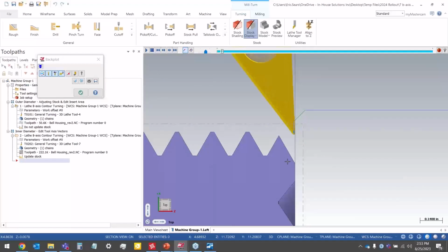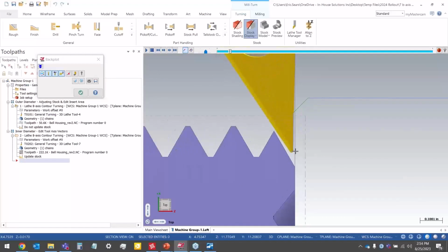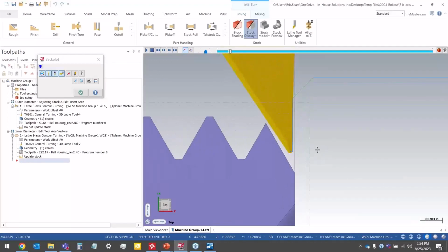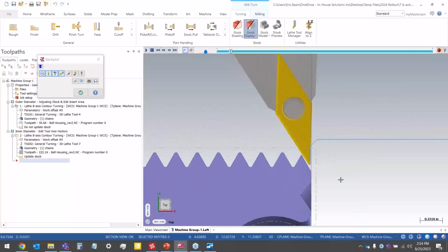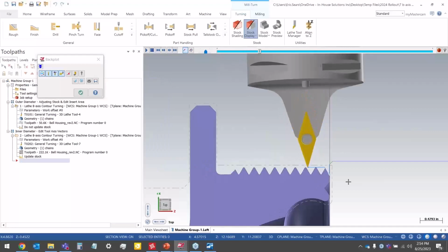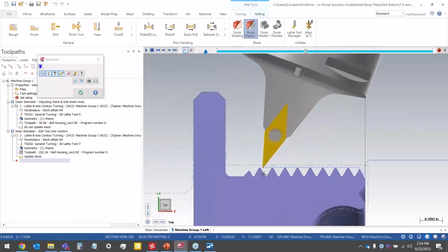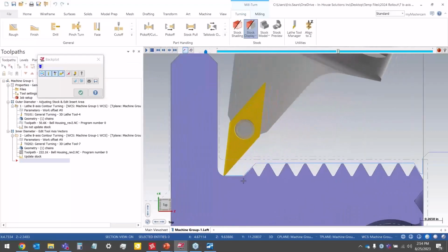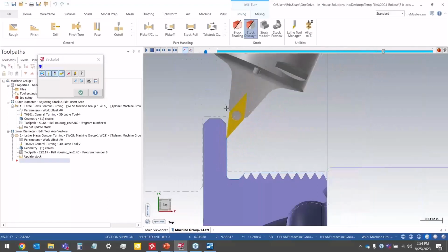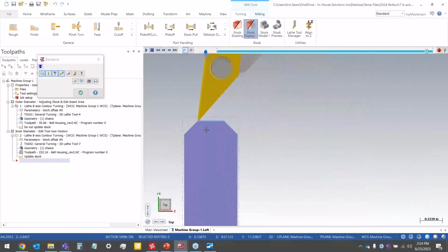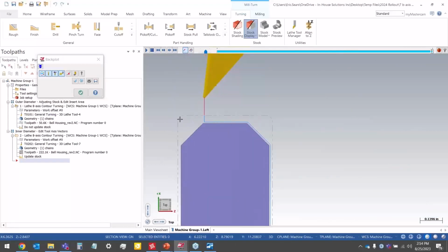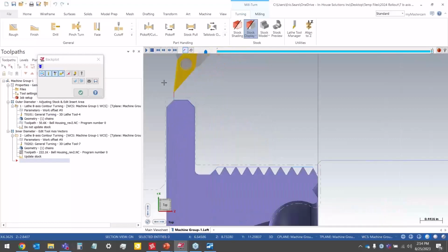And we can see here at the beginning, the way we're entering the cut, we're kind of not entering the stock how we would want it. And maybe the angle is not too great either. And then we go into this wall. And then our lead out as well. I would want to extend this edge just so that we go just in like negative Z off the end.